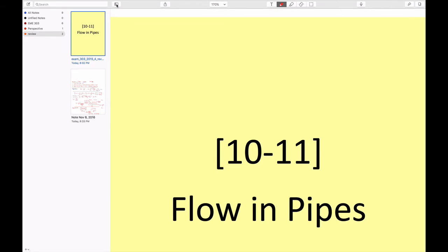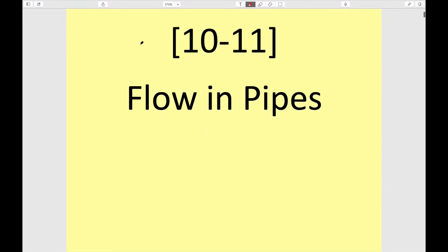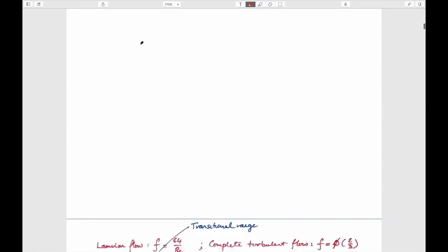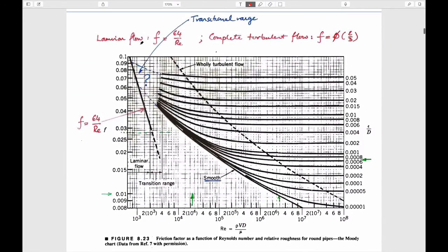So as we've done before, let's go through the material. I won't stop with the equations because we talked about those, and explain in quick summary detail some of the formats. We've used the Moody charts many times. We've talked about it already. We've talked about the fact that this transition in flows occurs somewhere around this region here at a magnitude of about, I guess that's not quite right, 2000, which I guess is here.